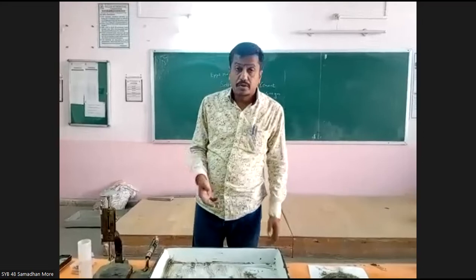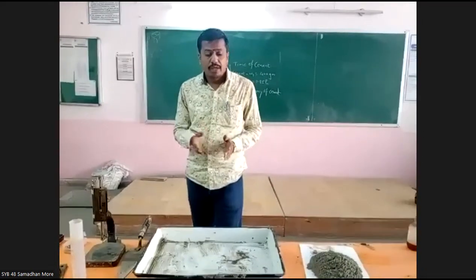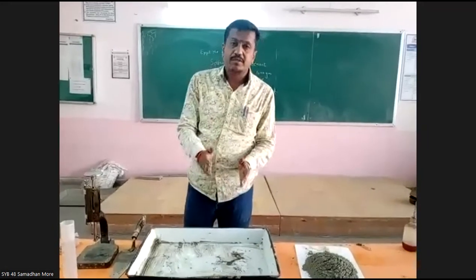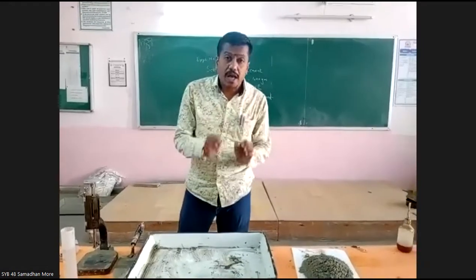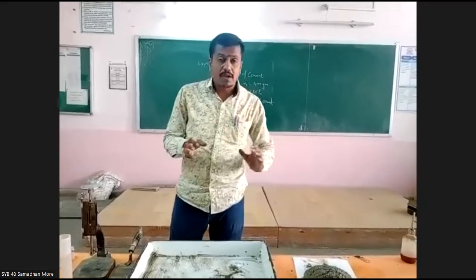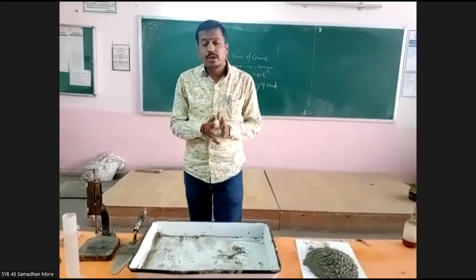Okay, so it is that stage of the cement when you add the water to the cement and the cement paste will just start to harden. So the time required for that phase is your initial setting time. Okay, and that we are going to determine.